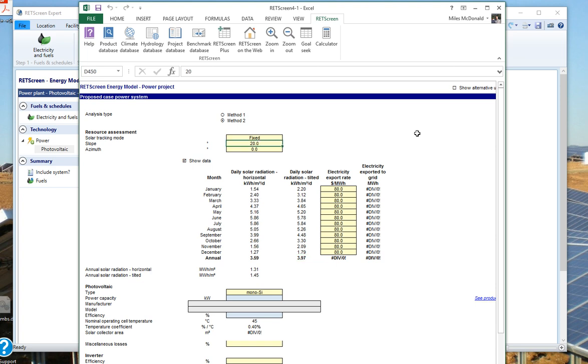This, incidentally, is what is known as scenario analysis. Let's keep going. 30 degrees. Still bumps up. 4.04 peak sun hours on an average day on an average year. Nice. Let's try 40. Oh, whoops. That's dropped down. That's no good. Better go back to 30. All right. Something else. July. 5.66 peak sun hours on an average day on an average year for every day in July. December. Average December day, 2 peak sun hours.